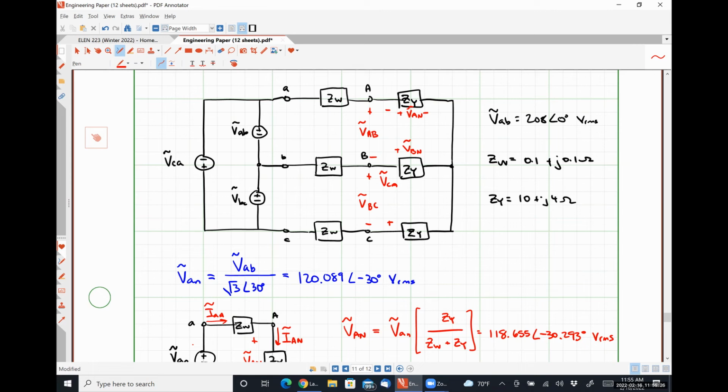On the right-hand side, on our load side, our terminals are given capital letters to differentiate it from the source side, but our voltages are defined in literally the exact same way. So this voltage VAB is the voltage seen between the A terminal and the B terminal, with the positive polarity terminal being A, the negative polarity terminal being B. This voltage VAN is the potential difference between the A terminal and the neutral terminal, which is the point of connection for our three phases in a Y-connected load.